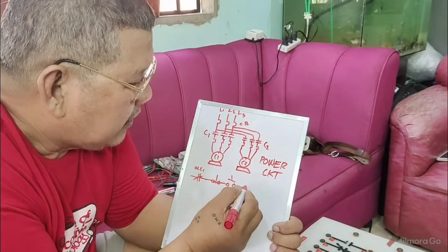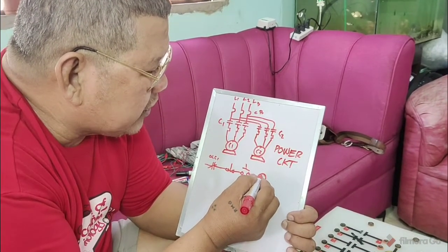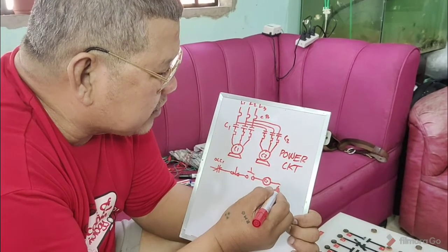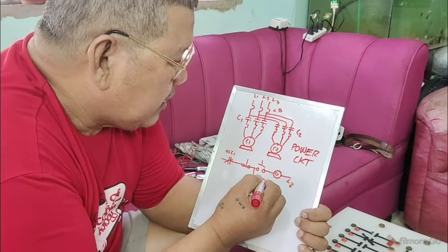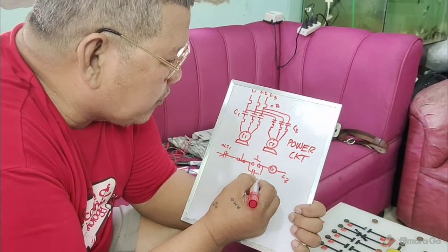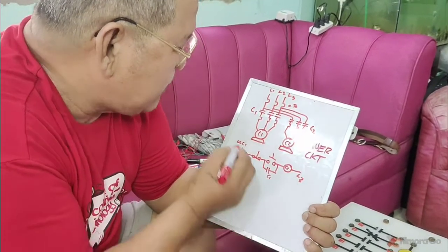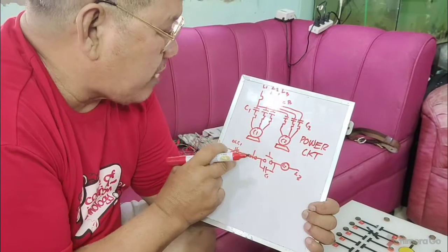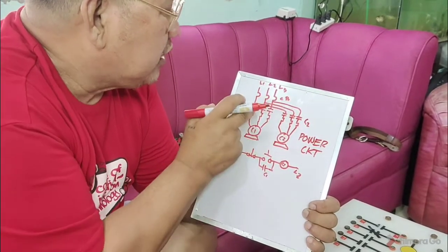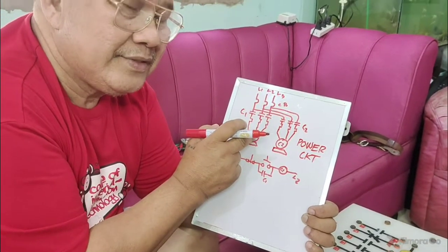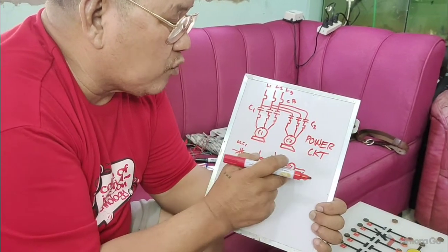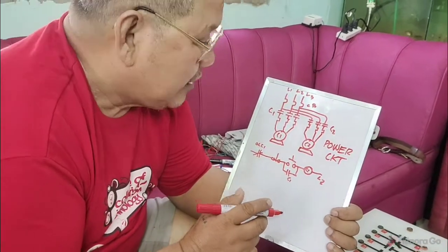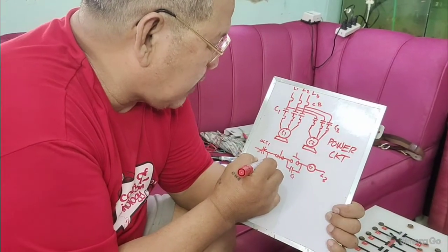Okay, that one. So this is your conveyor number 1 and this is for line 2. Then you have your maintaining contact, coming from conveyor number 1. So if I press the button here, this one will run. Now remember, conveyor number 2 will only run when conveyor number 1 is energized. So what would be next?